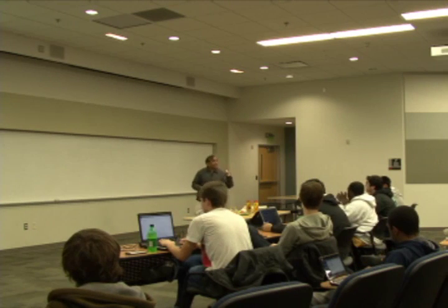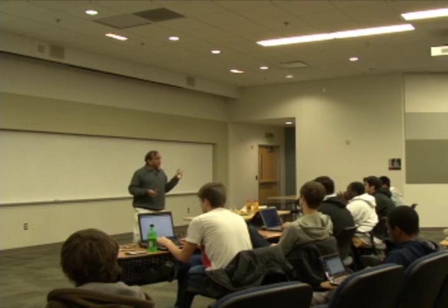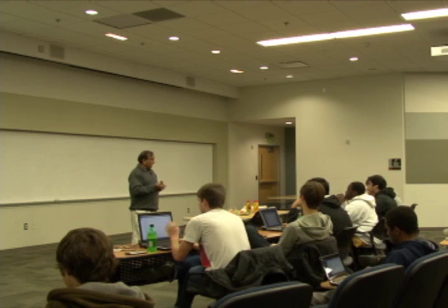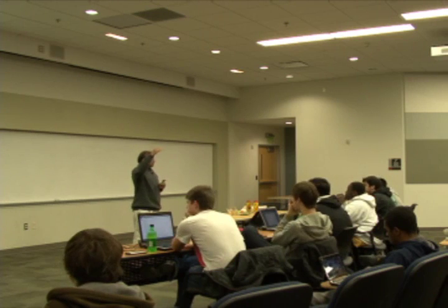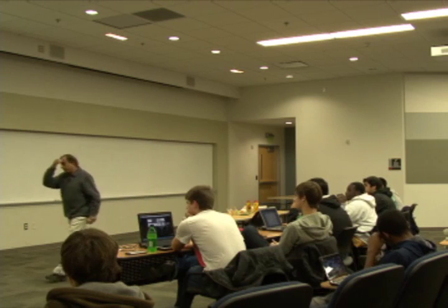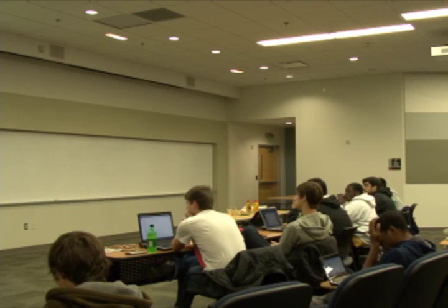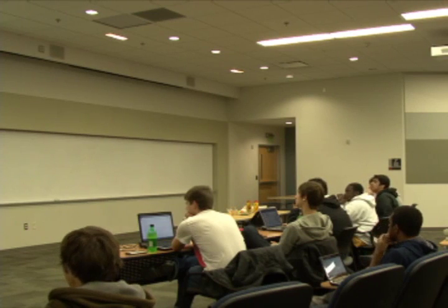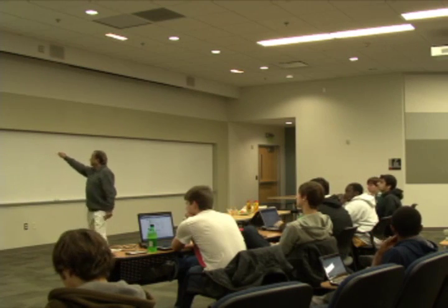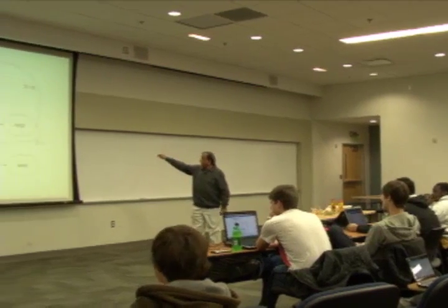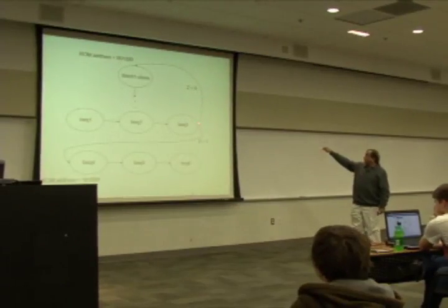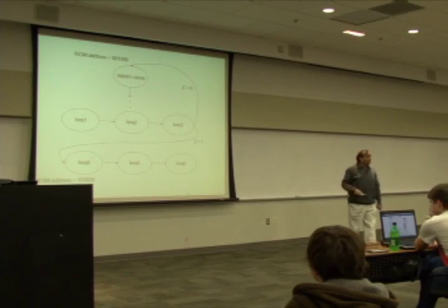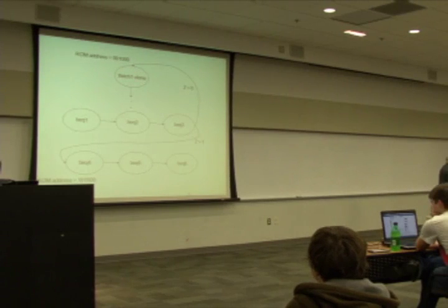So Z-bit, right? Using the Z-bit, we were able to say go to one of two different places, the normal fetch macro state, where the address may be something. This is the path by which Z is 0, and what you're going to do is go back to a clone of the fetch state, right?